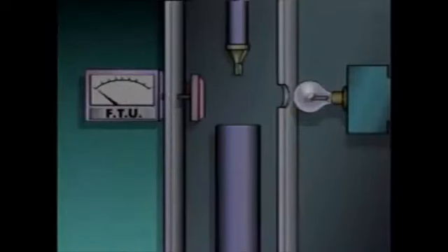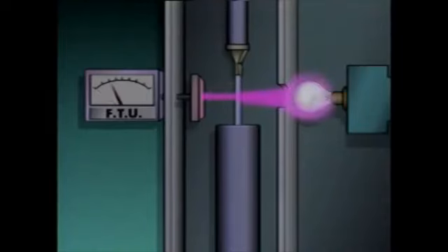A clarity analyzer that measures the turbidity of a mixture is called a turbidity meter. During the operation of a turbidity meter, the liquid being tested passes through a special restriction that forms the liquid into a flat stream. A beam of light is then directed through the flat stream of liquid. Suspended particles in the liquid absorb and scatter some of the light, but the rest of the light reaches a light measuring device called a photometer.